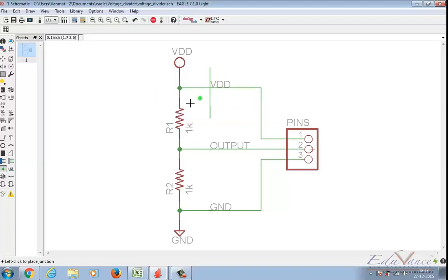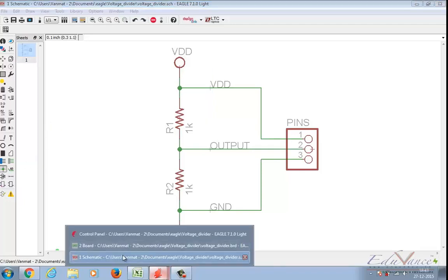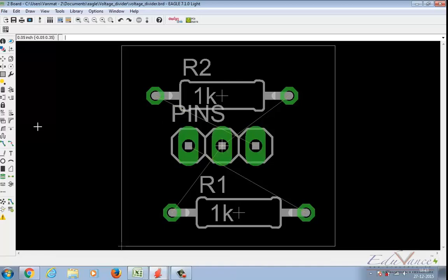No. When I merge it, only then it creates a junction or a node, and until and unless it won't. But the case is not the same when you're dealing with the board file. An overlap will short the wires, it will short the components. You don't want to do that. So the very first step of manual routing is to avoid such yellow crisscrosses.